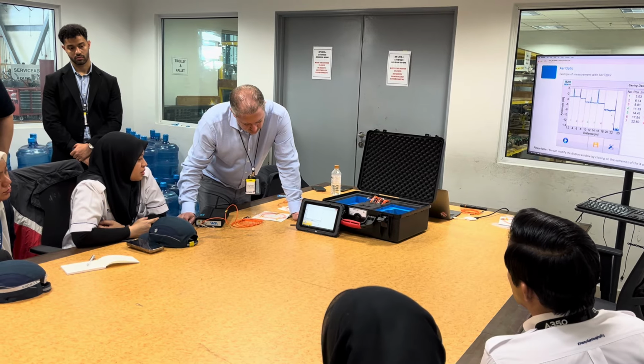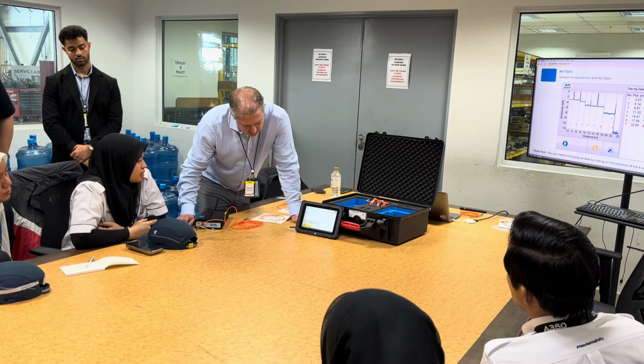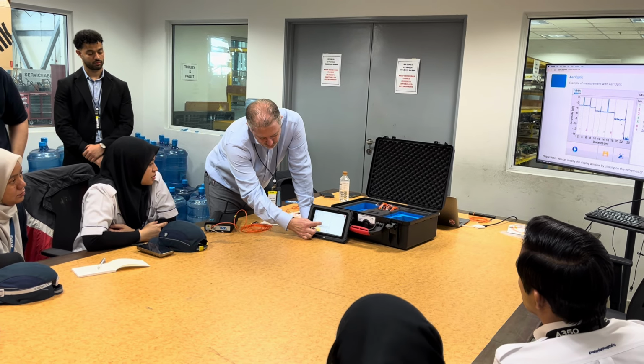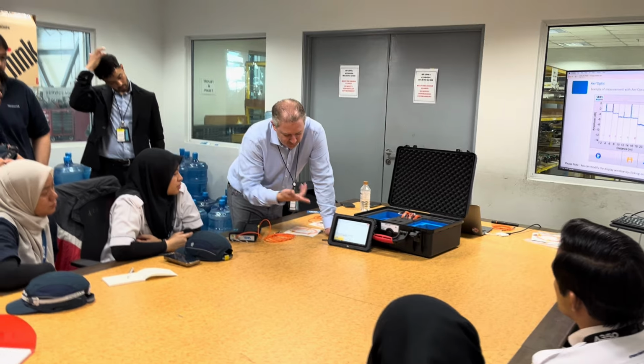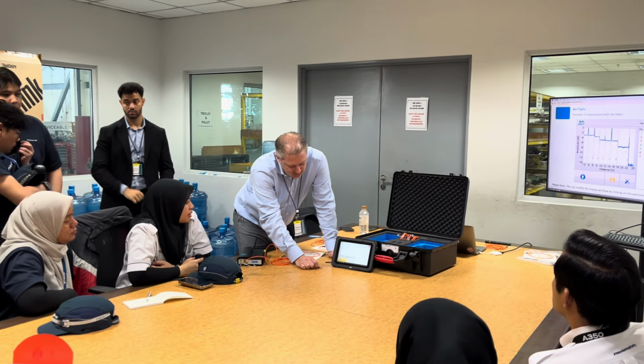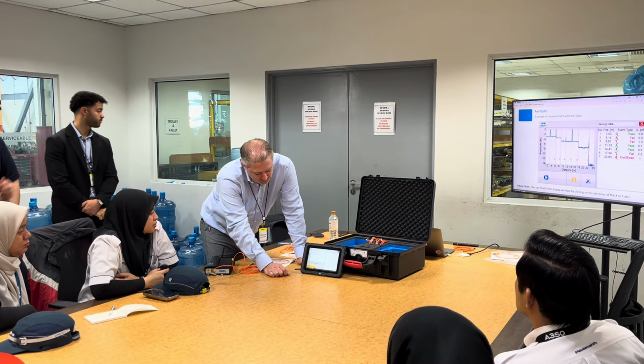Okay, and you see a big drop, which is the end of the fiber. The system is still scanning. You see small peaks because I have multiple reflections, as I mentioned earlier. But when you see this drop, you know that's a broken fiber or the end of the fiber.